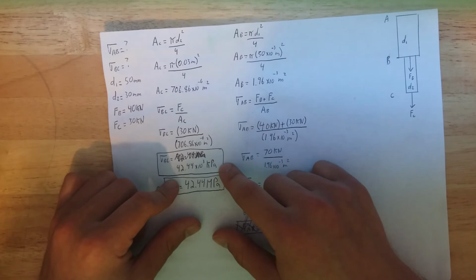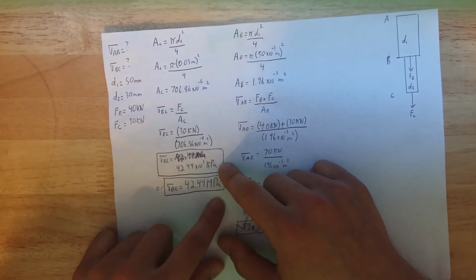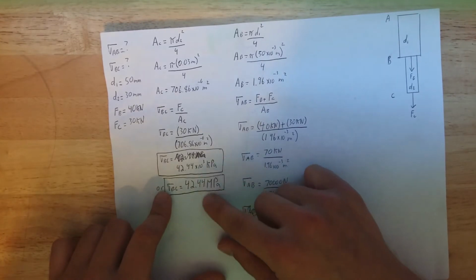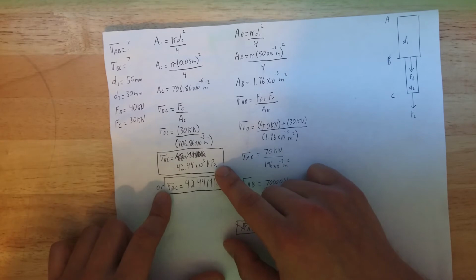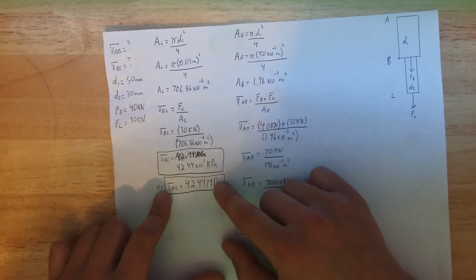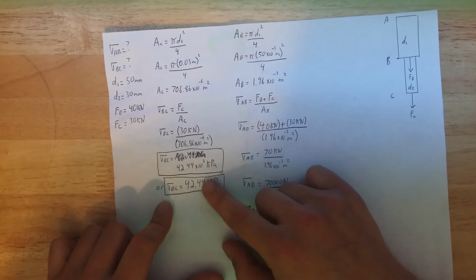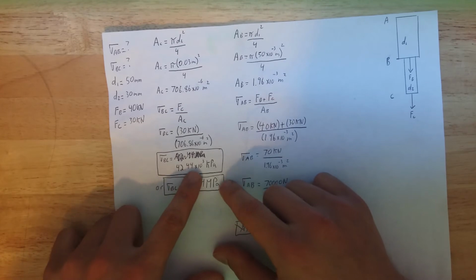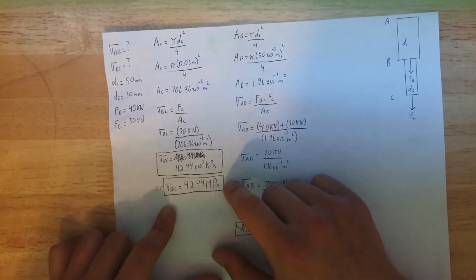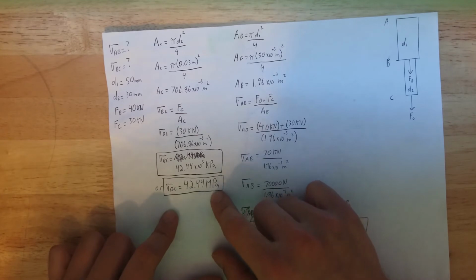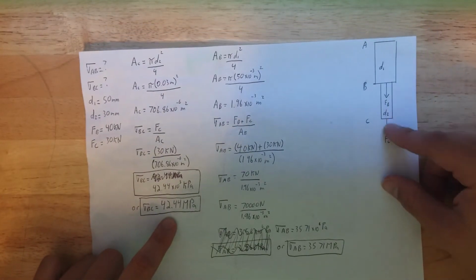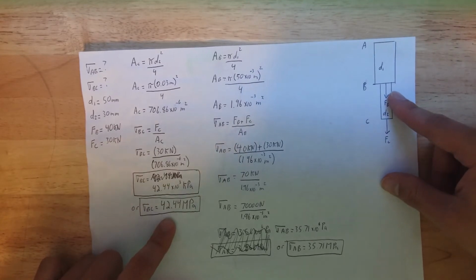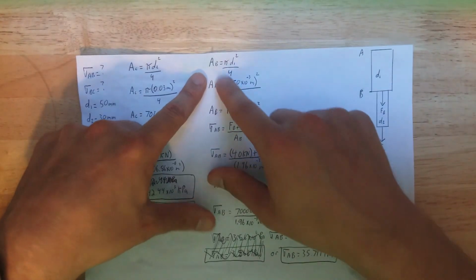Well, we could still convert that into megapascals. So that's what I did here. I got rid of this times 10 to the power of 3, and I just put a megapascal down. So kilopascal times 1,000, which is what that is, will give us a megapascal. Or I could have broken it down to 30,000 newtons, which would have given us 42.44 times 10 to the power of 6 pascals, which again is megapascals. So here's your answer for the first section. That's the maximum stress that this section could hold before it explodes, kind of deal. So now we're going to go to number 2.